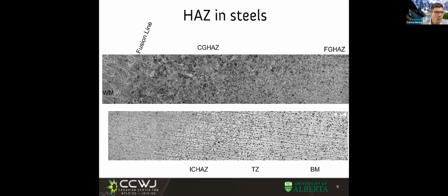Look, here we have the weld metal. You don't see a clear line for the fusion zone. Actually, I'm collaborating with some friends in China who are welding titanium, and they cannot see the fusion line, right? It's very difficult, but you get to see a change in microstructure. In the weld metal, you get to see these lines. So we're going to say the fusion line is here. This is not what I'm going to be worrying about in this course for the heat-affected zone.